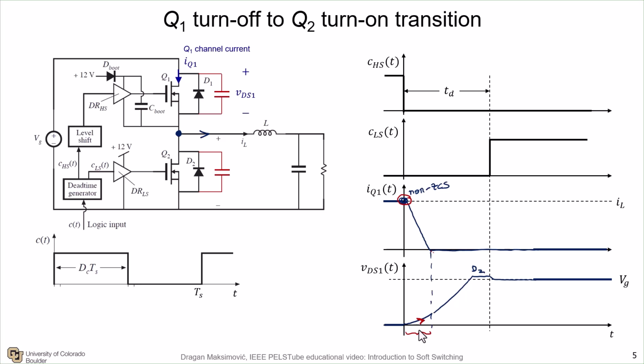The switching loss is relatively small because the voltage is increasing relatively slowly as the current is dropping down, and that slow increase in voltage is determined by how fast we are charging the switch node capacitances. That consists really of a parallel combination of the output capacitance of the two devices and any other maybe trace capacitances that you have with respect to the circuit ground.